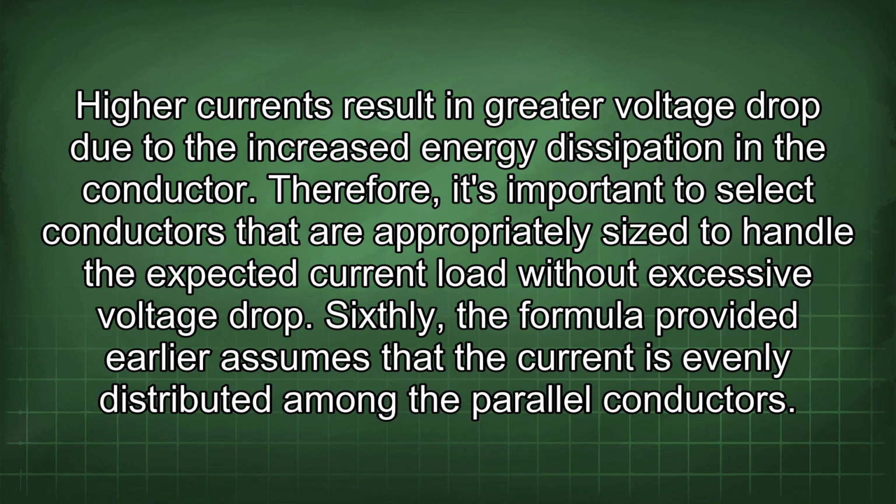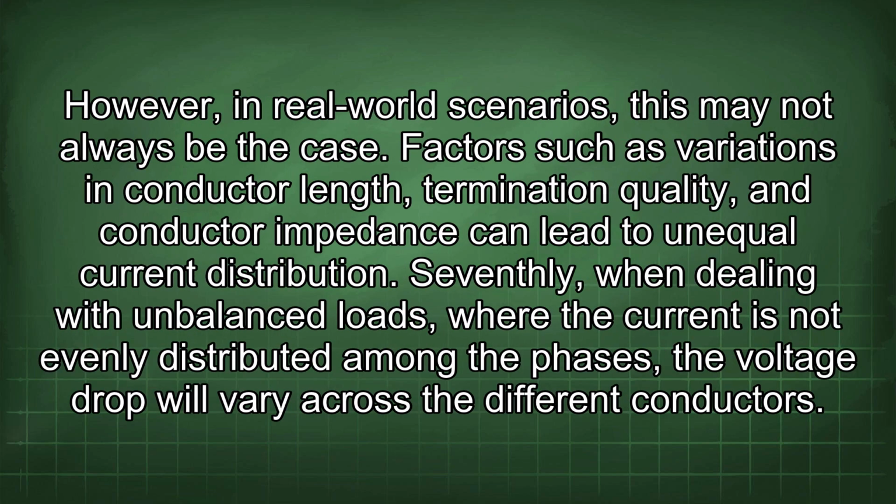Sixthly, the formula provided earlier assumes that the current is evenly distributed among the parallel conductors. However, in real-world scenarios, this may not always be the case. Factors such as variations in conductor length, termination quality, and conductor impedance can lead to unequal current distribution.